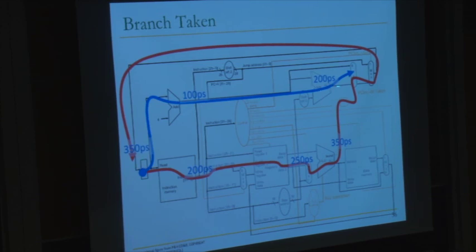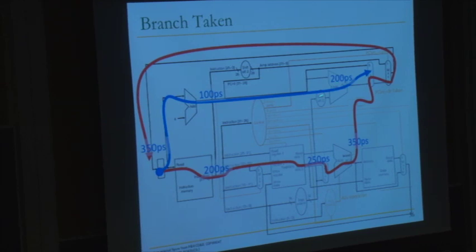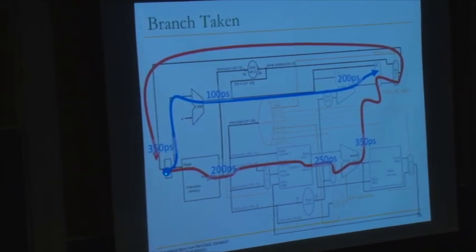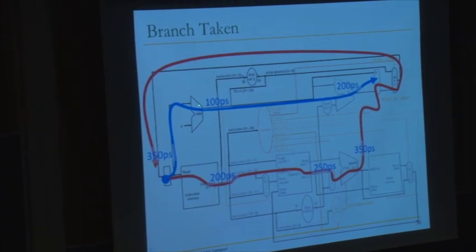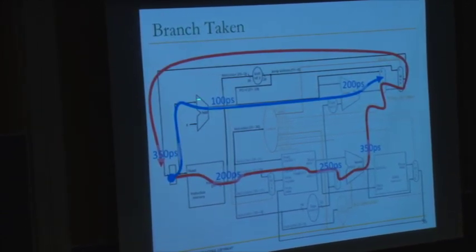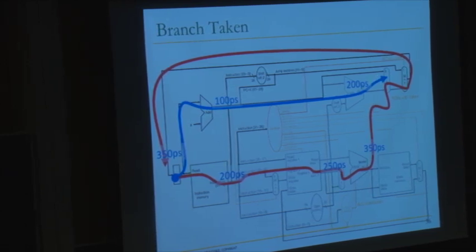This is the address calculation, right? You take the program counter and add to it a sign extended left shifted immediate. That gives you the address, which is the data input for this mux. And according to the numbers I told you, an adder takes 100 picoseconds, and another adder takes another 100 picoseconds. So within 200 picoseconds, the data input for this mux is ready.